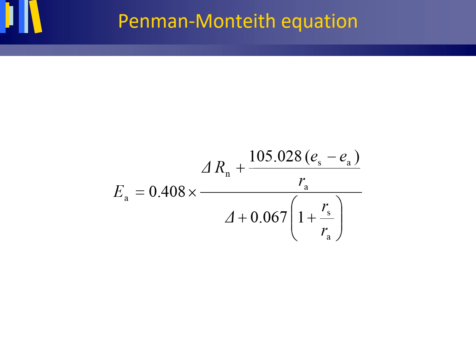The heat transfer into a soil, rock, or water body is relatively small and can often be neglected. If we set this to 0 and insert values for the constants and near constants into the Penman-Monteith equation, this is what we get as an equation. Actual evaporation in millimeter per day. Rn is the net radiation at the Earth's surface in megajoule per square meter per day.